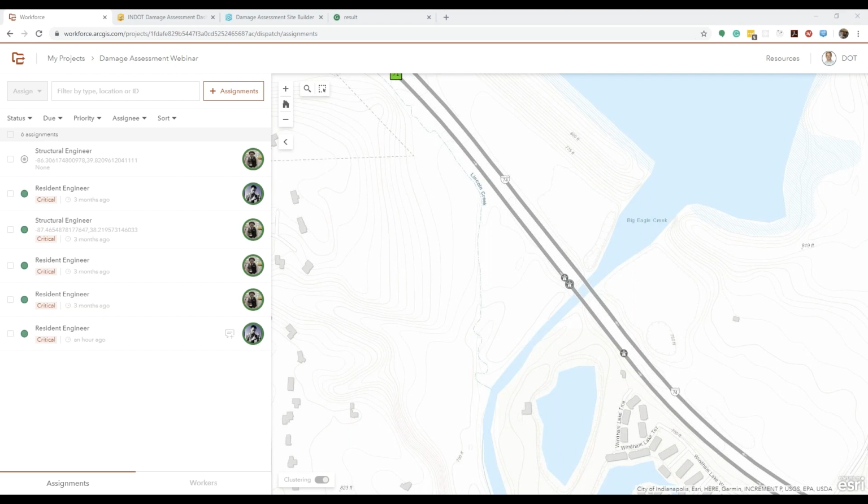distance to certain targets. Now, typically the optimal way to collect those targets is, I'm standing at, say, a sign, facing my phone directly at the sign face, and I'm able to measure the height of the sign and things like that. So that may not play very well with damage on a road or damage to a bridge, unless you're able to get into a position where you can safely capture damaged columns and things like that. But it does have the ability to measure the distance from where you are to where that damage is, and then calculates the difference, and you can incorporate that into Survey123 and do some calculations on the fly and do some markup photos. As you capture those things, you can mark them up with photography, and then submit all that data in your survey, so it is just part of that damage point or line that you collect in the field.